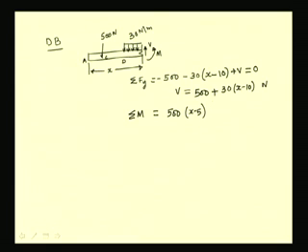So, we have 30 newtons into x minus 10 as the total load, which is acting at a distance of x minus 10 by 2 from this section, and we have the moment M, and the sum of these has to be 0.